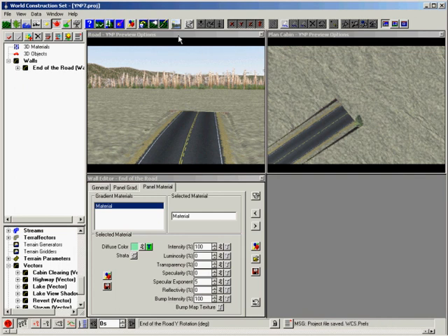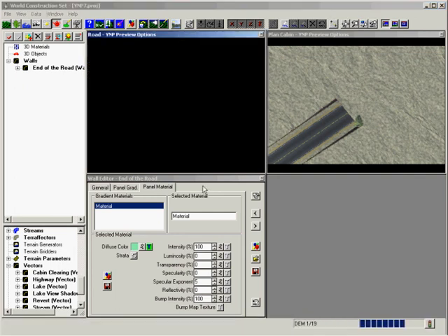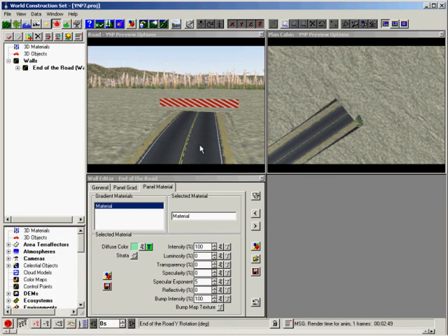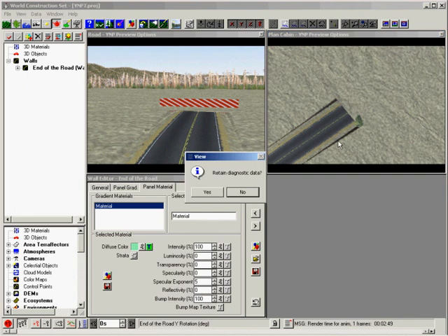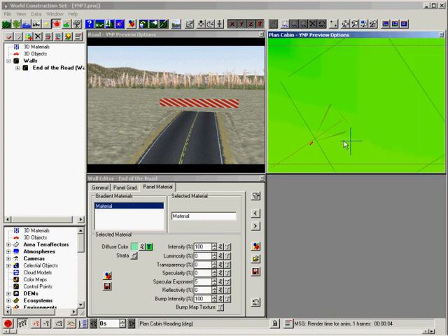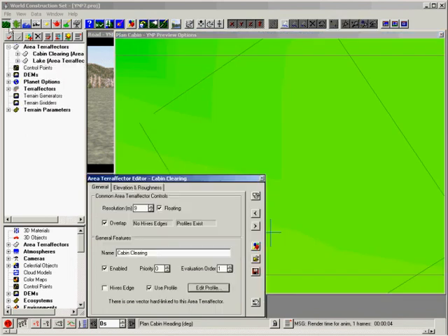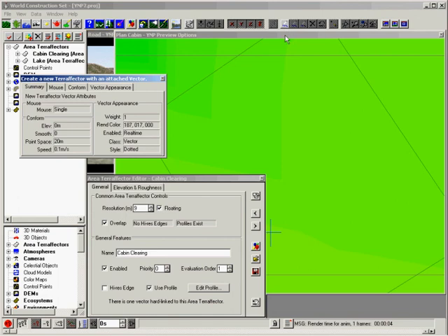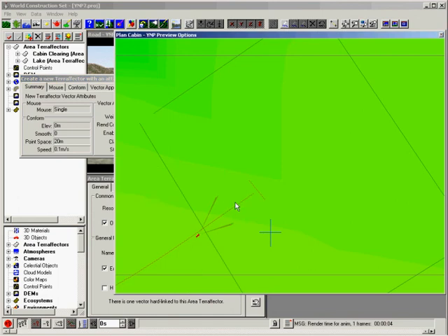Save the project and render a left perspective preview. Next comes the road for the development. Switch the planimetric view to real-time and zoom back a notch. Undock the view and drag it out for drawing room. Go to the Terrain Task Mode, select TerraFactors, and Create. Start a little out from the highway and digitize the vector.